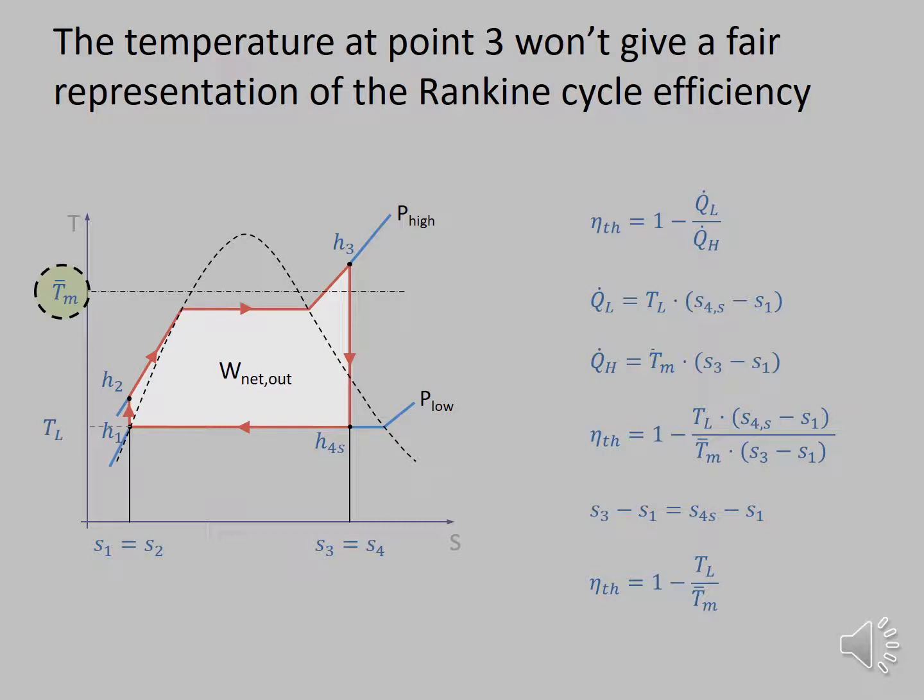So using this information, we can now again express the thermal efficiency of the cycle as this, basically just putting in the equations that we used, recognizing also that S3 equals S4 and S1 equals S2, which means that we basically get the same expression for the thermal efficiency again, in terms of temperature. So the same reasoning that we applied on the Carnot engine, looking at temperature differences, can now be applied to the Rankine cycle because of this equation basically.